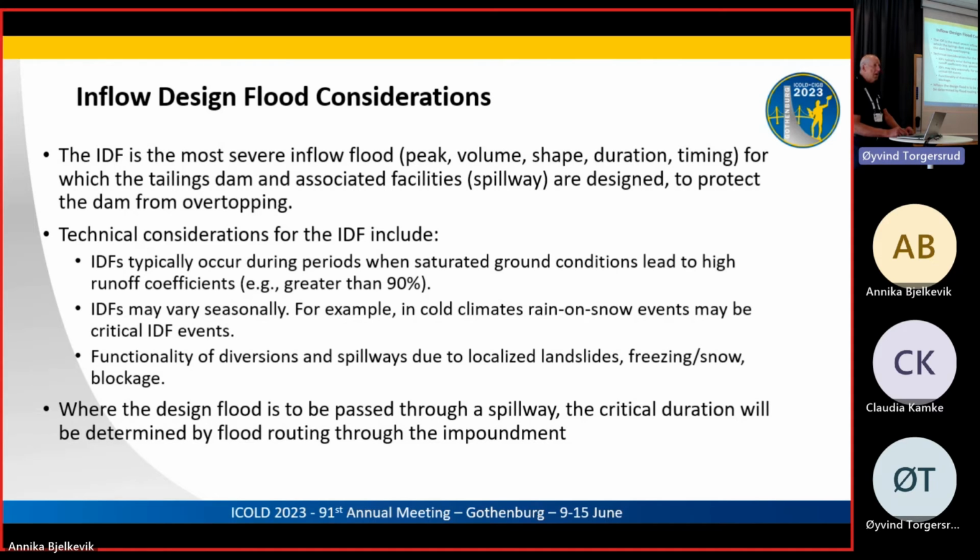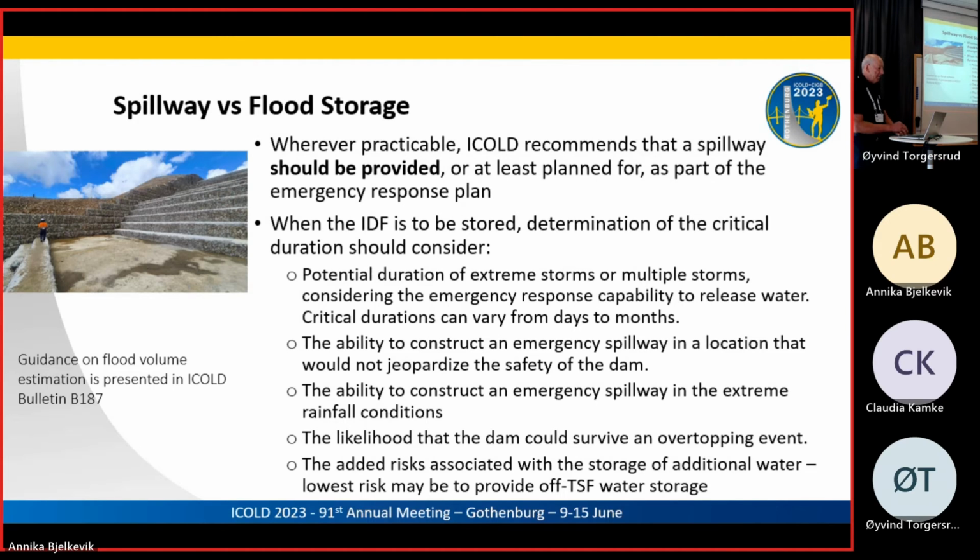If we do have a spillway, we've just got to go through the normal hydrology of calculating the routing of a flood through to determine the spillway capacity. So, spillway versus flood storage. In our bulletin, we say that a spillway should be provided, or at least planned for as part of the emergency response plan. So that's our recommendation.